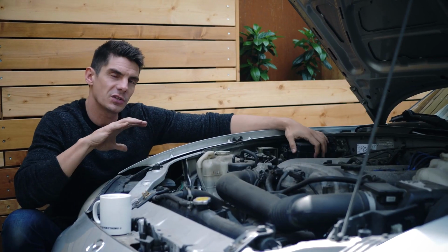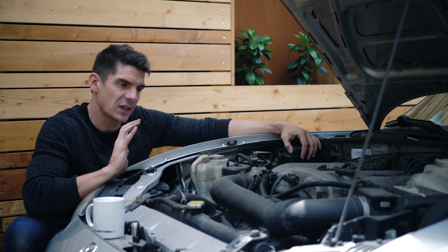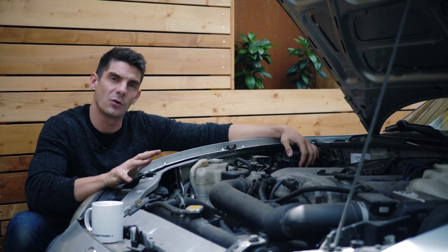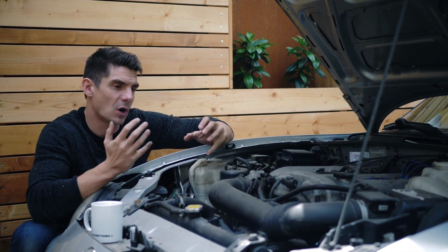Now, to check a relay, in theory, you could check it on the car, but you're much safer, particularly on a relay that's controlled by the ECU, to take the relay out and test it off the vehicle. Then you need to identify your wiring connections.